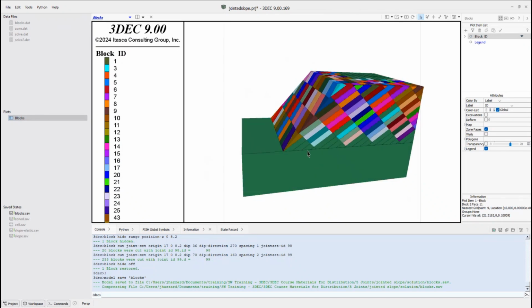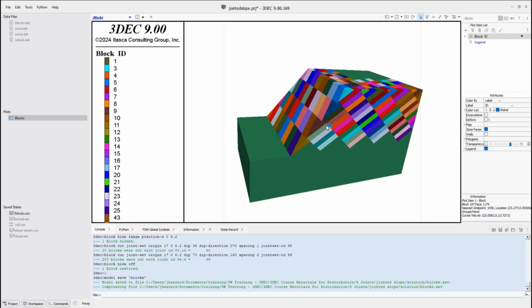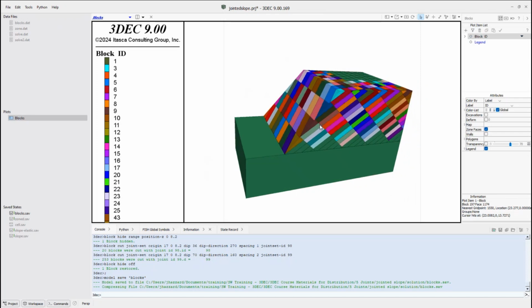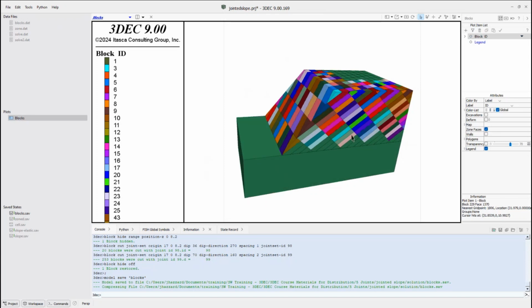So we've got a contact here that's joined. This doesn't necessarily form a nice contiguous piece, so it gets a little bit confused about how to do the coloring. When you use that block join by contact on, it's great because then the join, which we put here, does not become unjoined. But it's a little bit disconcerting when you plot the blocks by ID because it tries to plot things that it thinks are joined.